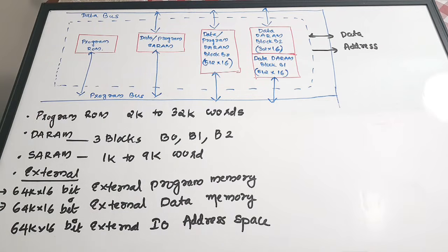It is used to permanently store the program code for a specific application during the manufacturing of the chip itself. So during manufacturing, we write this PROM memory. The processor has an option of boot loading the content of the PROM to internal or external RAM during the power on reset.